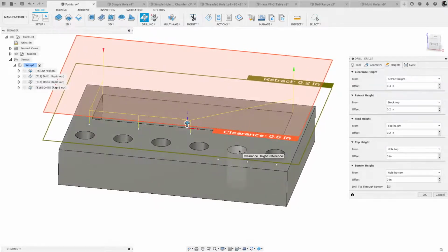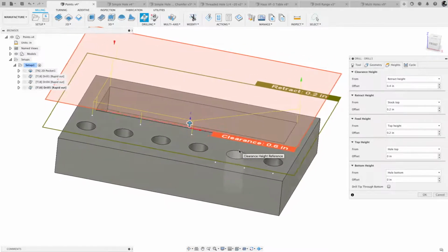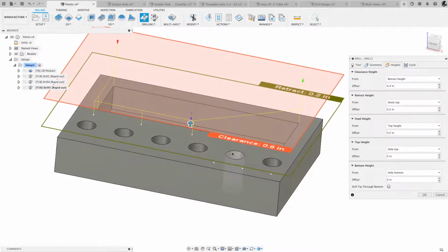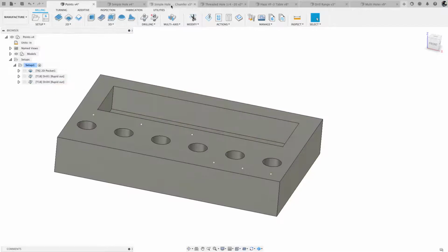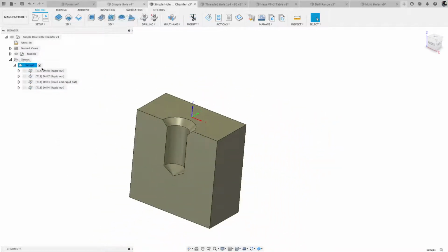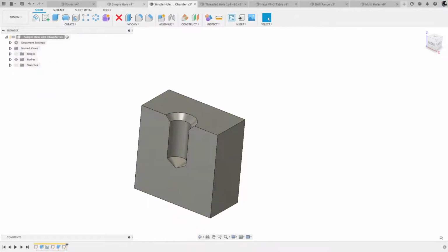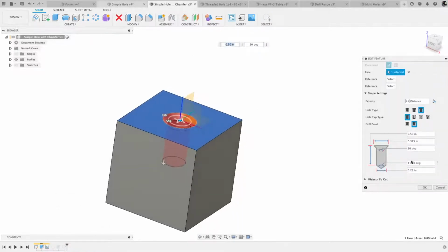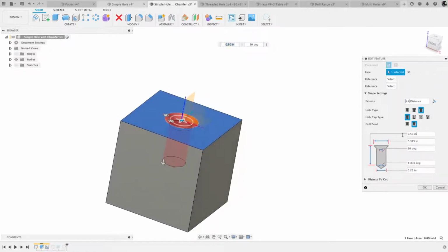So leverage the model, guys. Leverage the model that your customer gives you. Because anytime you move a hole, change the hole diameter, change the hole depth, like we did on this one here. I can even, like I said, come down here. If we go to design, if we change that hole depth and even that chamfer, so here the depth of that hole was 0.5.